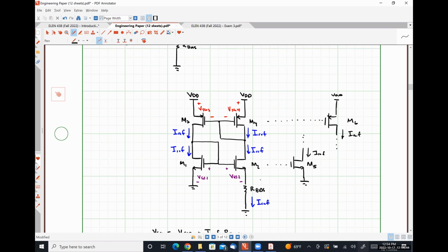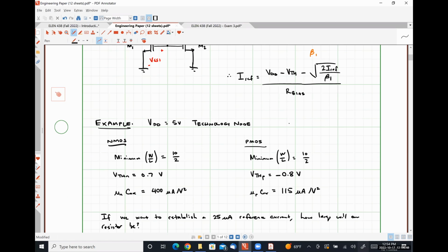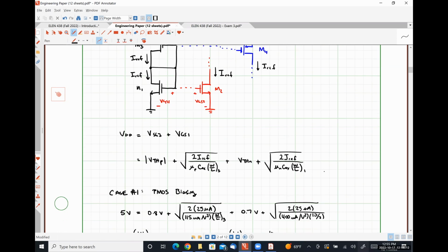So in this case, we go back here. If we were using 10 by 2 NMOS transistors, we could use 30 by 2 PMOS transistors to get effectively the same mobility. 3 times the width would get us in the ballpark, and everything would work pretty great. Okay. All right, so the last thing that I want to talk about for today then is